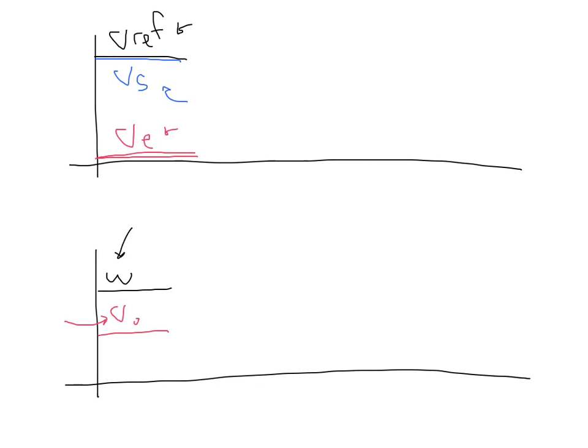Now let's take a look at what happens if at this point in time everything's sitting constant. If we start going up a ramp with our robot, we've applied more torque to the wheels, it takes more power to go up that ramp, and so our motor speed has started to drop. And we don't want it to drop, we want to be at a constant speed. So what's going to happen here? Well, as omega starts to drop, Vs is going to start to drop as well. We know that Vs is simply a constant times omega from our model of our speed sensor.